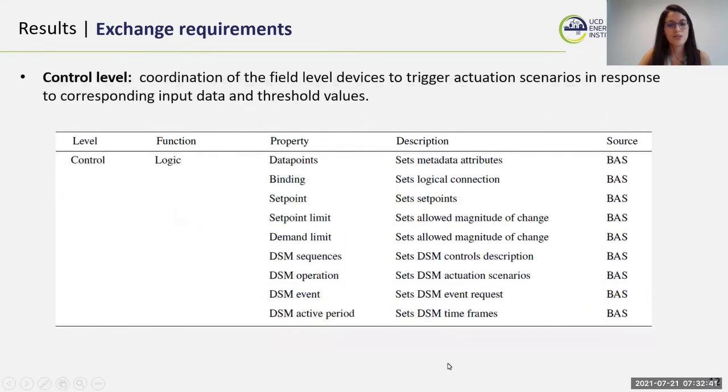In terms of the control level, so the idea here is to represent the logics and define the exchange requirements for representing the logics. So in terms of data points, having both physical and virtual data points, defining set points, defining the logical connection, so relationships between input and outputs of the device, the control scenarios, so actuation scenarios for the operation, and the events from the demand side management, and time frames as well.